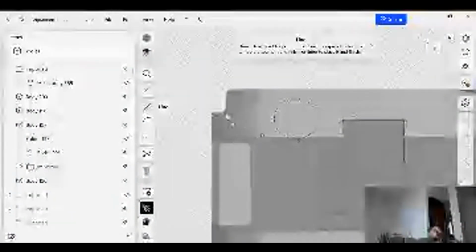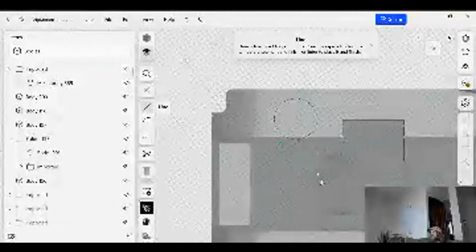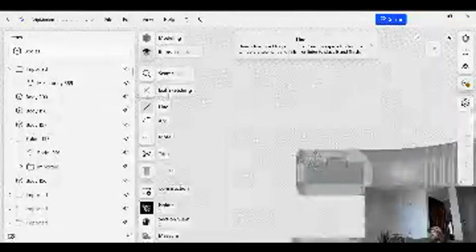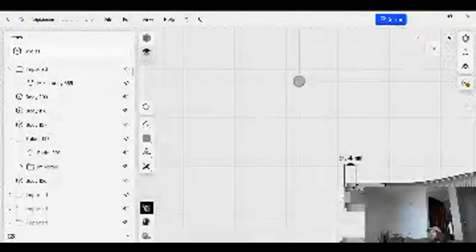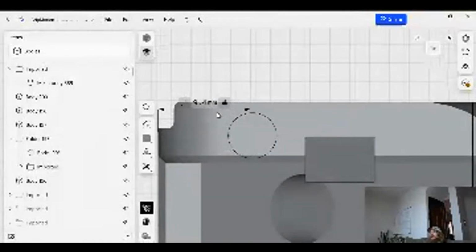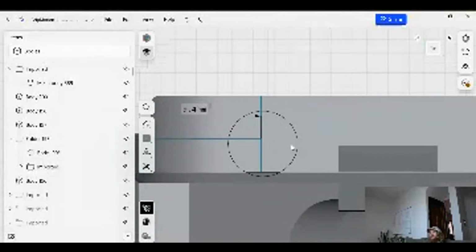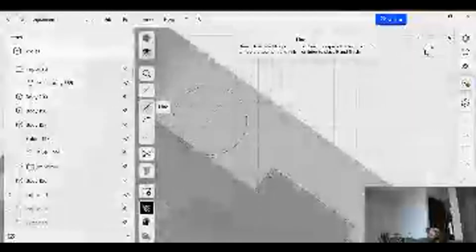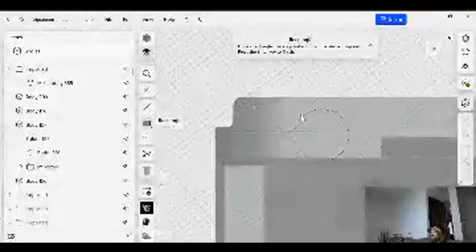Square up. Sometimes you'll get the lines running parallel to your object, even though your object is laid out clearly on the XY axis. And you're like, what the heck? How, when I click on this to edit this, does it throw me to a 45 or roughly there? Anyway, come up here to the top right corner. Click this. It's at least going to straighten you out. Square you up. Not much I can do about the grid pattern.